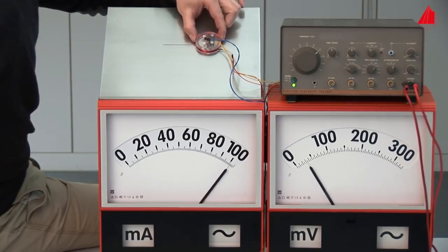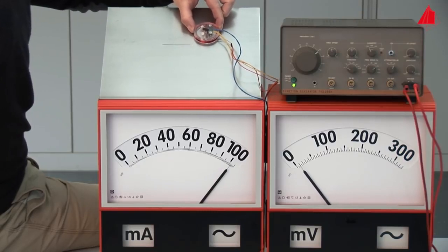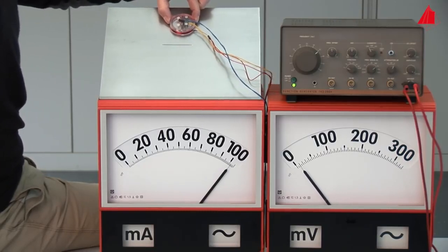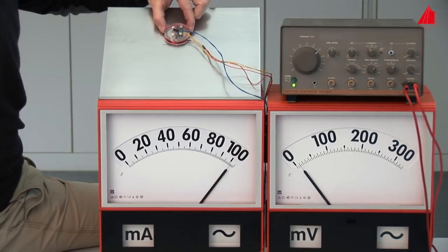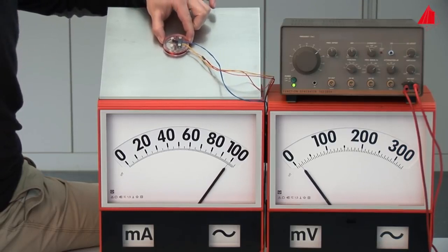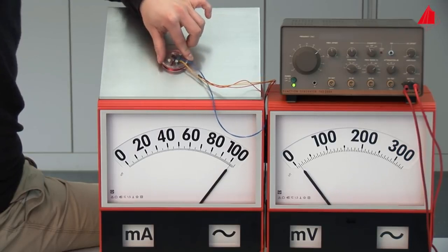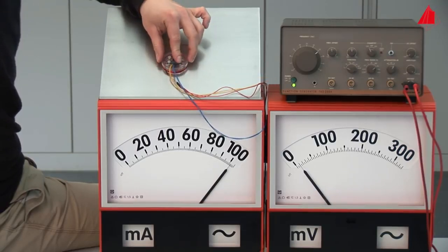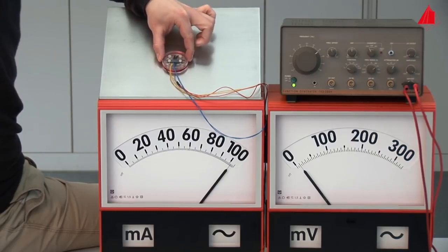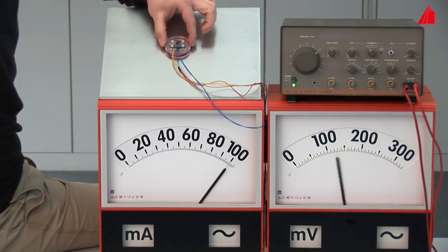But one point should always be kept in mind. The 2 D-shaped receiver coils must have the correct orientation for saw cuts and cracks. Otherwise you measure only little or nothing at all. If the orientation of cracks is not known, the probe is rotated by 90 degrees after the first pass and the test piece is scanned a second time.